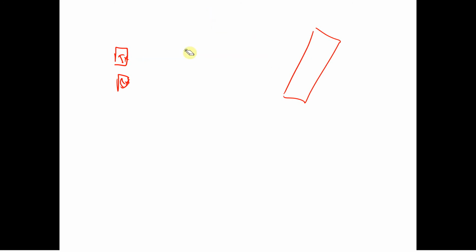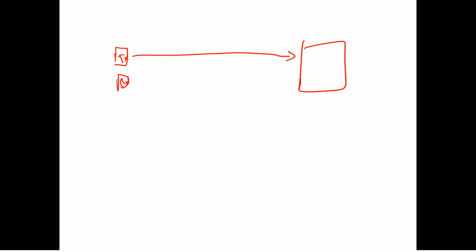The other issue is that it could possibly be triggered by noise in the environment. So if it transmits and it's waiting for the echo, and in between that time, there's another loud sound that spans multiple frequencies in the gym, like if someone drops a chair or something like that, that external sound might reach the receiver at just the wrong time. And again, this is why it's useful to not just take one distance measurement, but take 5 and confirm that they're all reasonable, and either average them or look for outliers in the data set and throw them away.